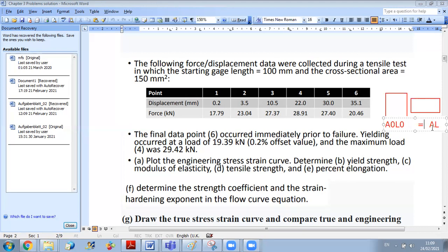Then, to get true sigma, we get the actual area and can compute true stress based on the formula F over actual area. Or if you already have the engineering stress and engineering strain, you can use the relation between the engineering and true values. Actually, if you remember, when we did the demonstration of all the formulas, we based ourselves on conservation of volume because we found that A0 over A is equal to L over L0. Yes, okay, so they are equivalent.